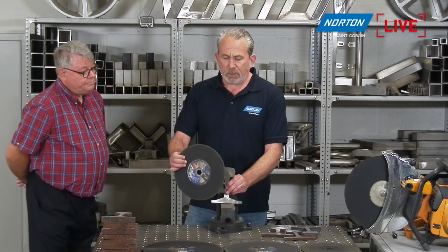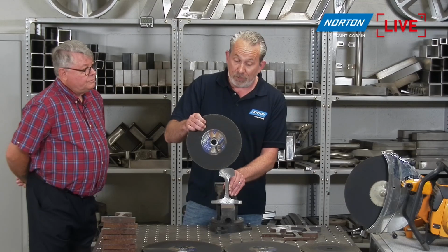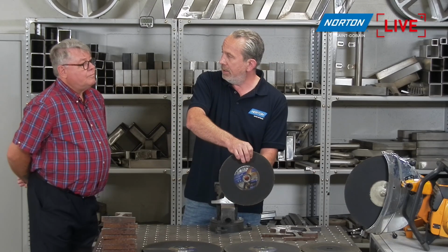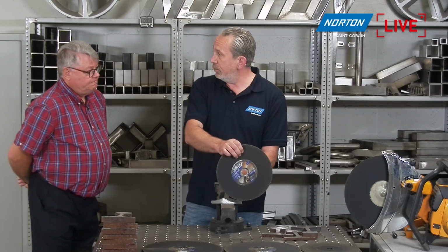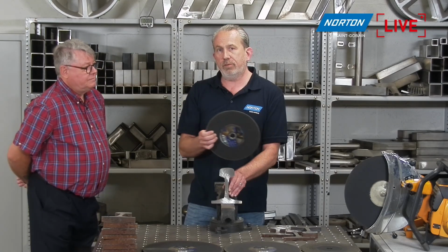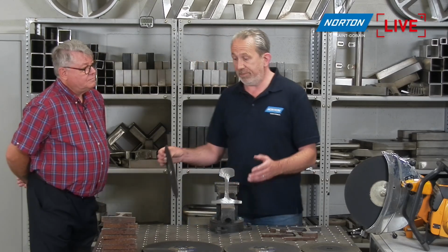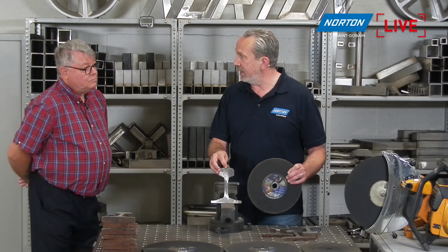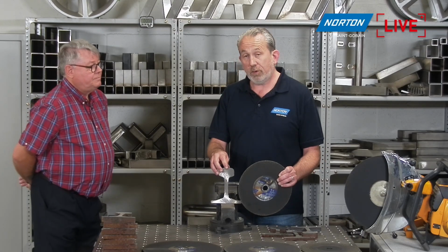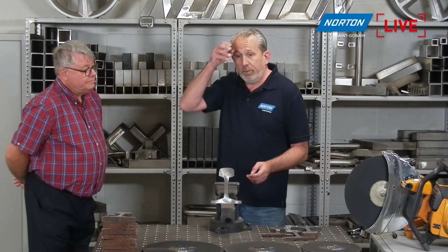We also said that when we're cutting, we never go over the top of the track and cut from the opposite side. That's a big no-no in the industry as well. Always from the one side, and the reason is lack of control and pinching of the blade. Spraying the debris up into the air towards the overhead cables is also not a great thing to do. So we make sure we get through from this side, and if the blade's small in diameter, we dismount and go again from this side, through the foot first again, and meet to complete the cut. That's a little bit about the top tips for cutting.